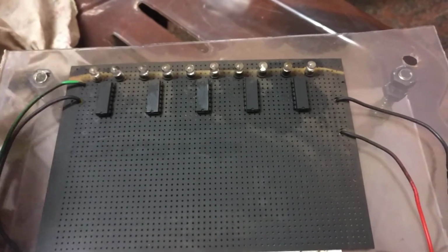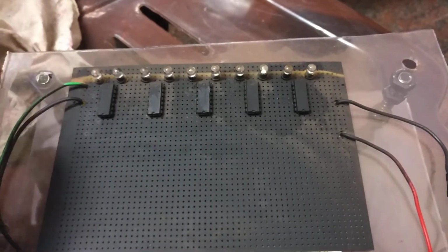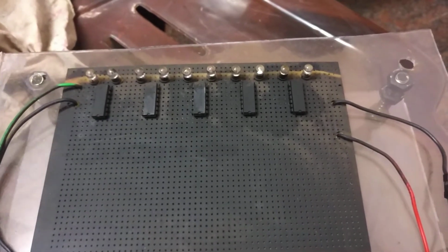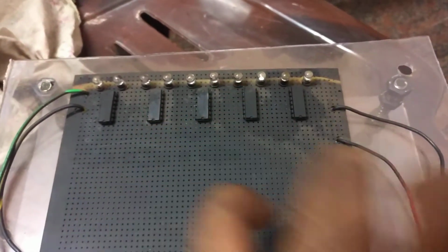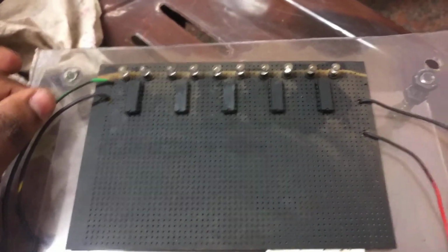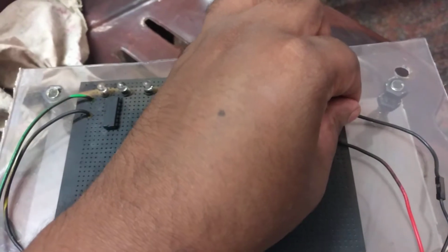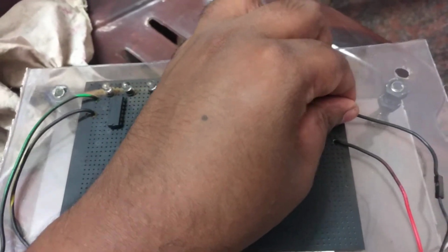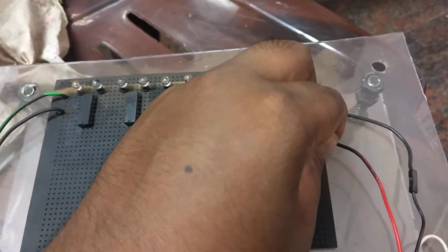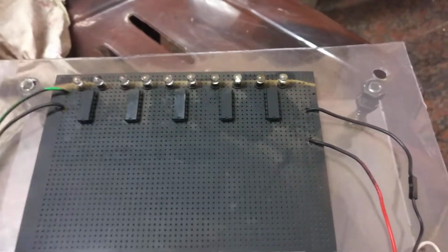So this is basically the Q, and the Q dash is given to the next register as the clock, and Q is given as the input, and it shifts. At last it goes here, and here the data just goes away. Here we have the clock signal, and here we have the data signal, and here are two wires. This is the black wire, this is the ground, right? And here we have the positive, this is VCC, and I would like to give it around 3.3 volts because I don't have any current limiter resistors here.